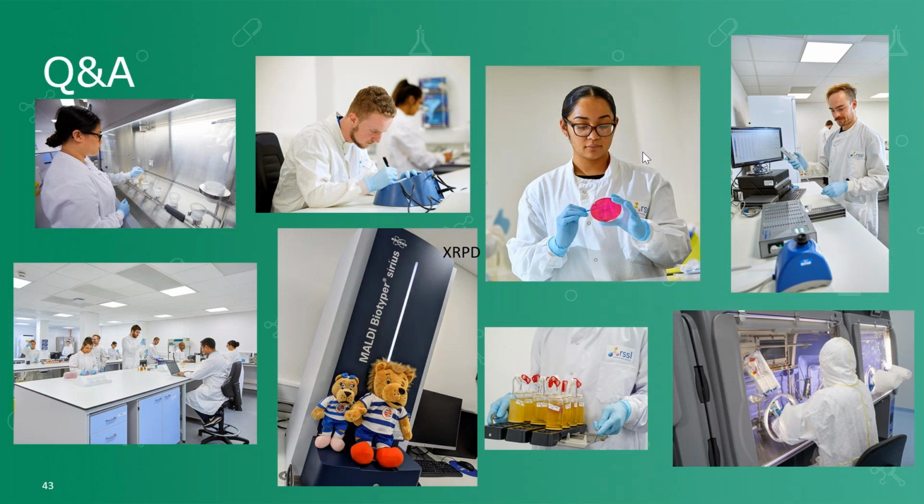For purified water and for non-sterile manufacturing, then you can expand that, say, over a month or something. So I think with a lot of things, the frequency is determined a little bit by the criticality of the activity and the importance of the data, making sure there's regular data coming in every day, and also with the degree of control that you have. So a risk-based approach would be the answer, and I'd go with those frequencies personally, but your risk-based approach might produce something else.